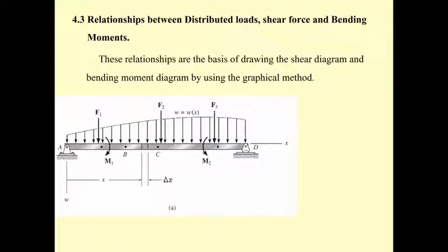However, when we move to another location, the values of the normal force, shear force, and bending moment usually change. For this kind of change, we need to see how the shear force changes along the length of the beam and the frame. That means we draw the so-called shear diagram.